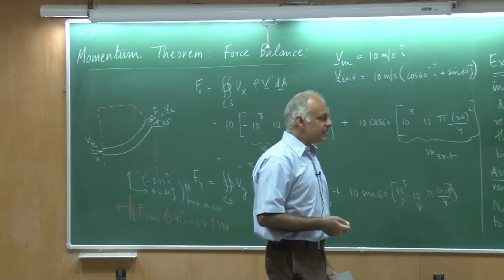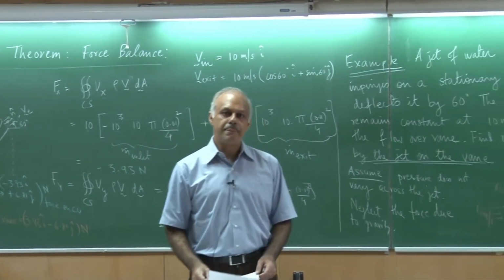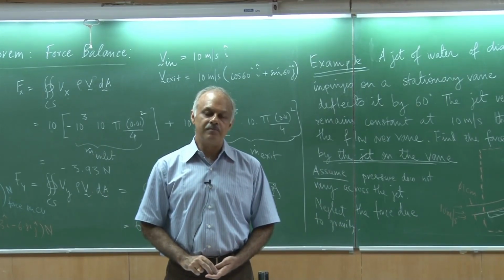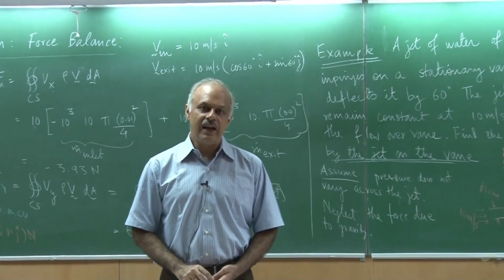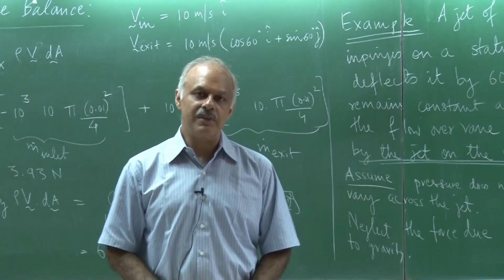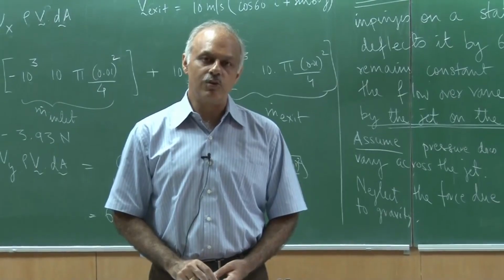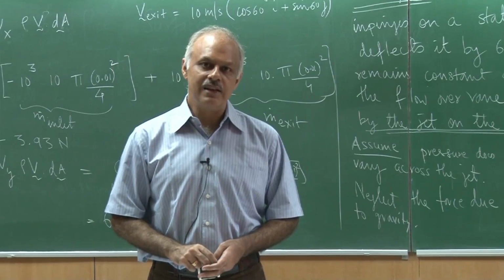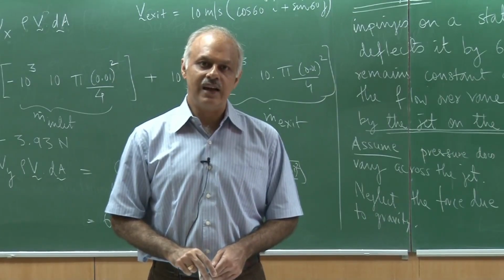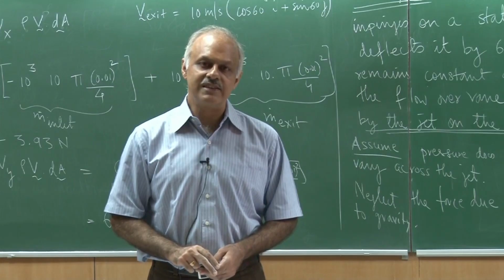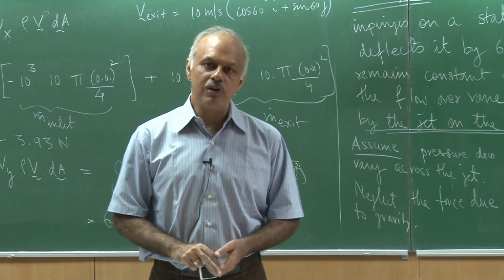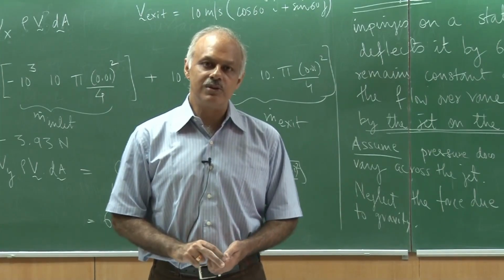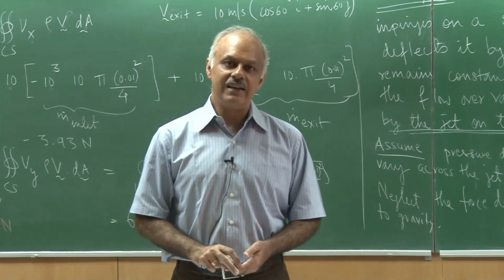Alright, so in this lecture what I have tried to show you is essentially how the Reynolds transport theorem could be used to give you the momentum theorem, and how you could relate the force acting on a control volume to the rate of change of momentum. We took one simple example, and this was for a steady flow, and the vane was stationary, the control volume was stationary, and we took two different control volumes and were able to see how to apply this theorem to that. Hopefully, you will be able to practice certain problems and then understand a little bit more.